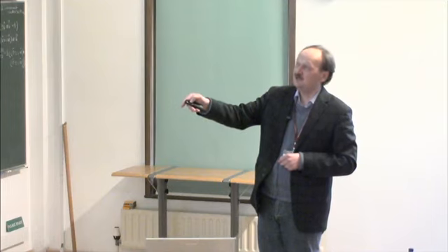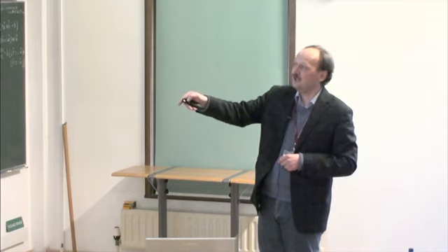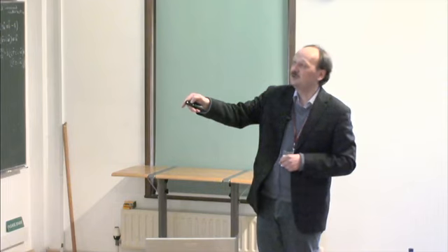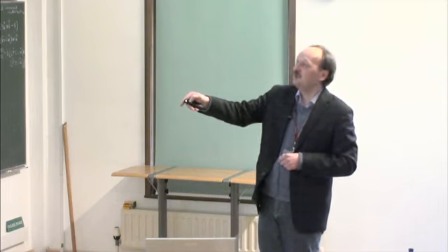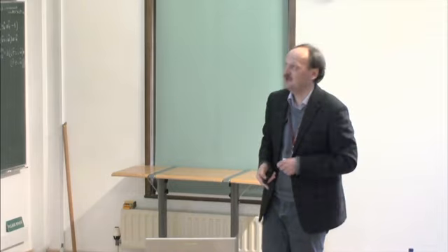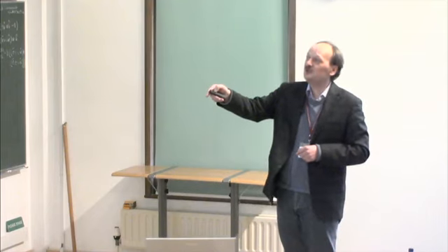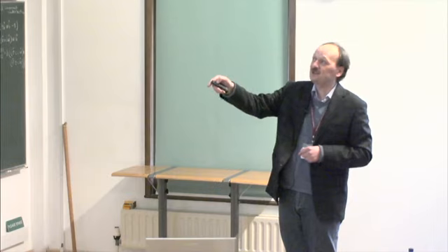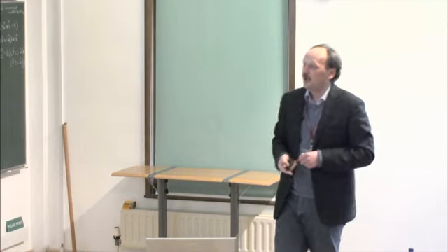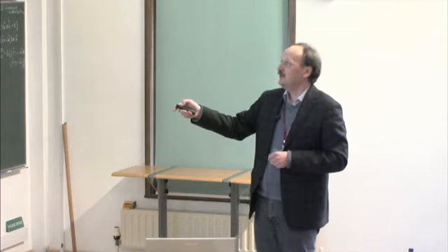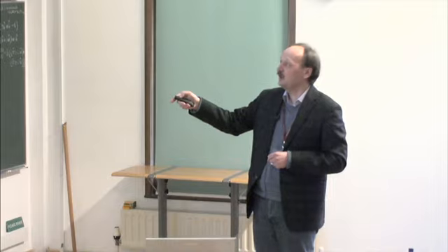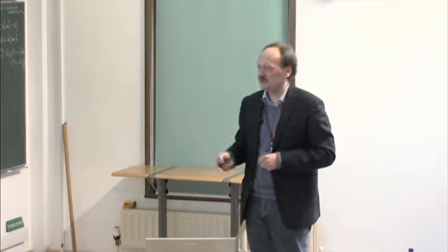But for the elastomer case, we see that the shape nicely returns to the original strain of 1 when we cool the system down. So basically, here only when we held the system a very short time of 4 nanoseconds, we have the retention of the order. And here we say the time window of our reversibility for our model elastomer is 40 nanoseconds.